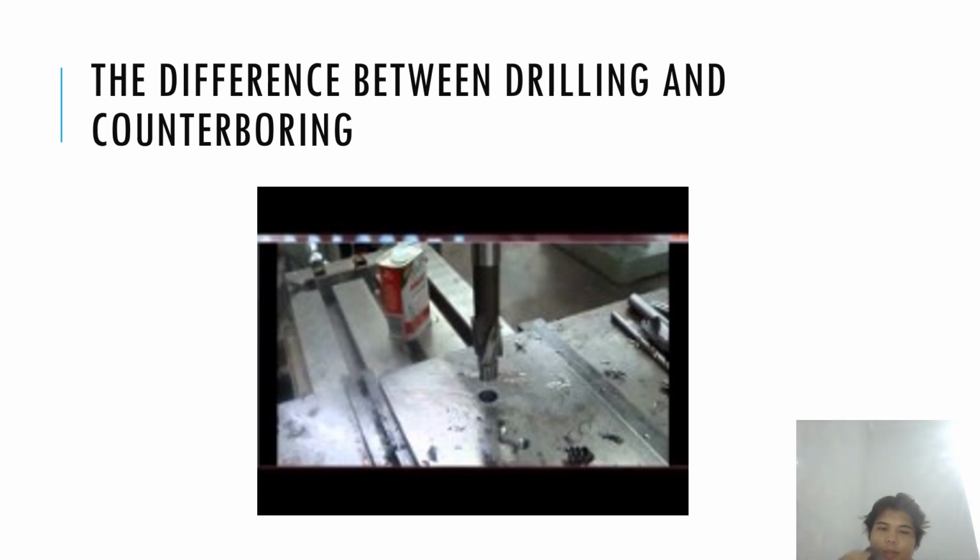This one is basic drilling. This has a pilot of 406 thousandths. Drill a hole so that the pilot will fit down into the hole. And because our chuck will run out a little bit, it's okay to drill it a little under the size of the pilot, but the pilot will still fit.